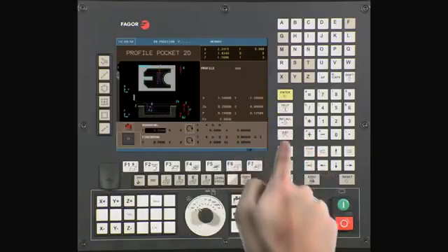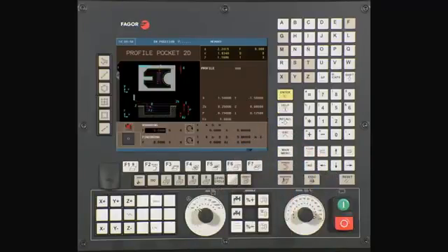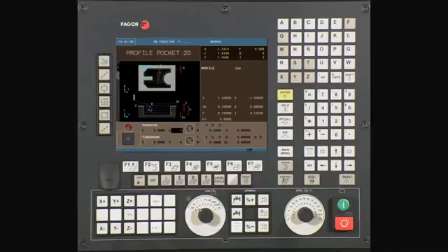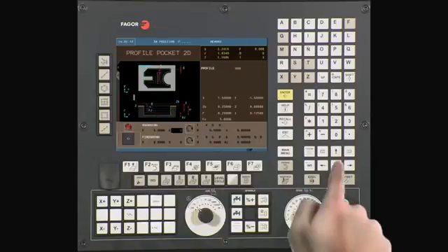F. This is your roughing feed rate along the axis. In this example, we are using a value of 5 inches per minute. Press Enter to continue. S. This is your spindle speed. In this example, we are using a value of 2000 RPMs.